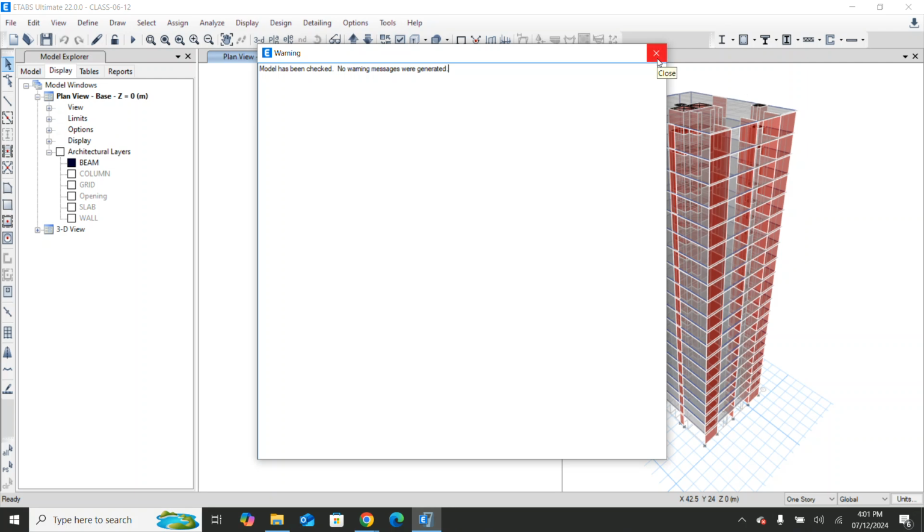Now this model, there is no warning message, madam. What kind of warning will come in the models? Model warning, basically, in the same way I said, we have the steel frames over there, okay? Then mistakenly one concrete frame we also placed on top of that, or some intersections, like model merge, two properties assigned over there, or one steel bar is there, then one concrete bar, both having some kind of intersection. This type of problem is model related, not the analysis.